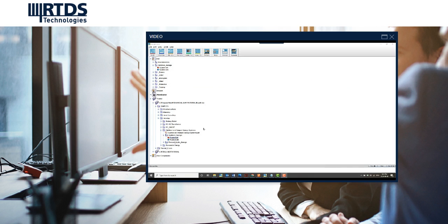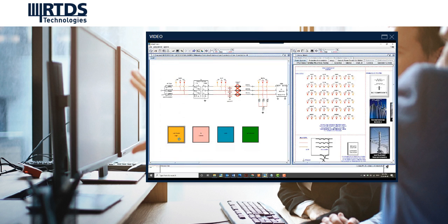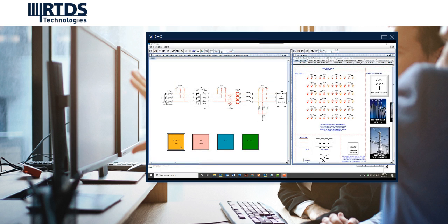Last but not least, I will show our fuse case. It's under the protection automation section of the main step. This is a newer case which is aimed at demonstrating protection coordination between various devices in a distribution feeder. And there's a focus on branch fuses. So the idea is to reduce the blowing of fuses for temporary faults.